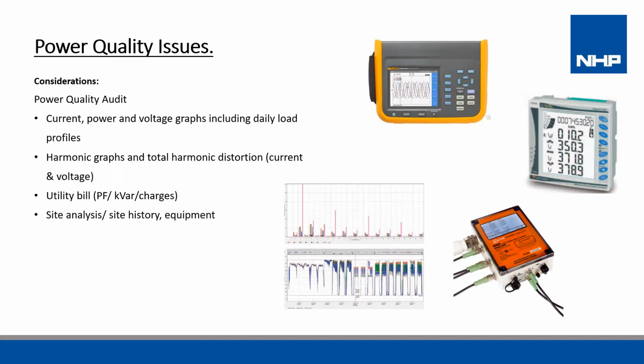So looking through a site, there are some common and simple methods that can give a general idea of on-site power quality. To start off with, it is best practice to check the voltage and see whether it is within the SIR limits, the state and territory rules, that is, service and installation rules.